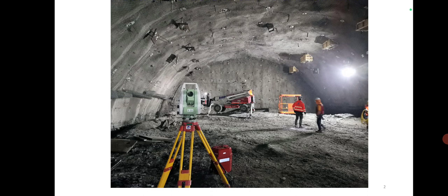Then we do a lot of surveys before constructing the tunnels. Preliminary surveys include geological, geophysical and geochemical methods, aerial photography, and seismic surveys, in order to know the topography of the area, lithology, hydrological conditions, and the occurrence of different secondary structures, reserve rocks, etc. We will also propose alternate tunnel routes. All these are done in the preliminary survey.